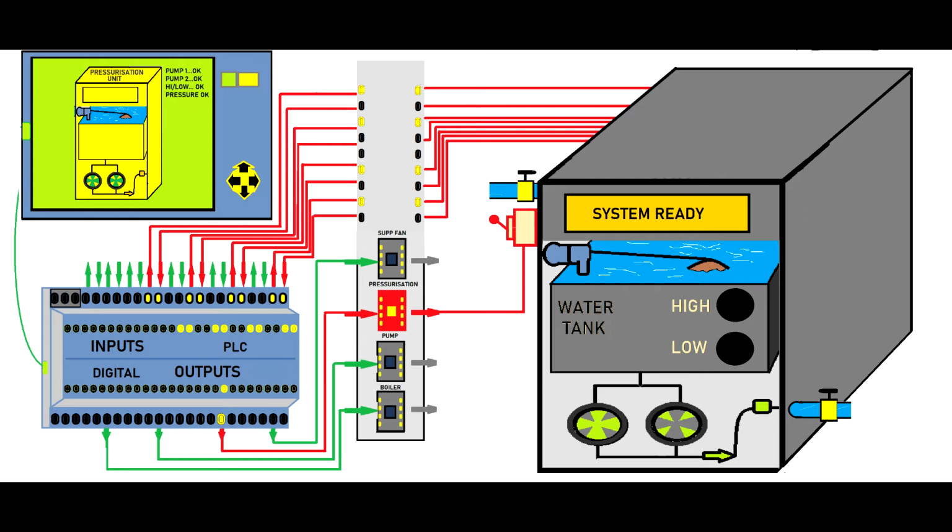Also, you'll have high and low water level probes that will send the information to the pressurization unit printed circuit board, and that information can be transferred into the programmable logic controller, which will send the information to the HMI. As I said, there are levels of integration. Then you have the two pumps, as you'll see down in the round circle. You have an arrow, which is a one-way valve, and then a little bit on the top you'll have the pressure probe, the pressure transducer, which will tell the pressurization unit about the pressure in the system.